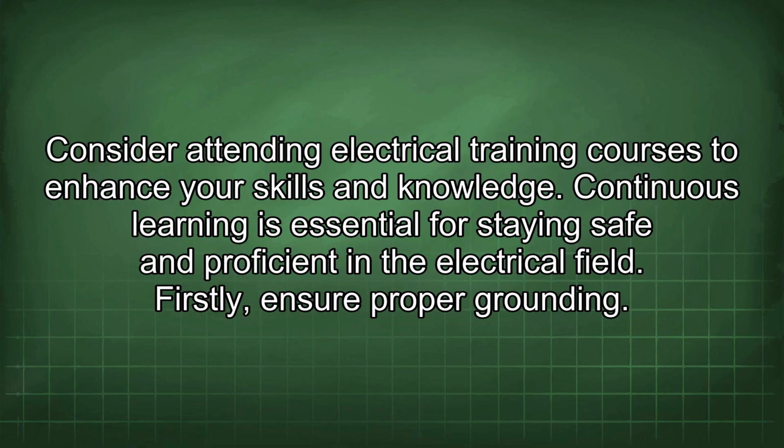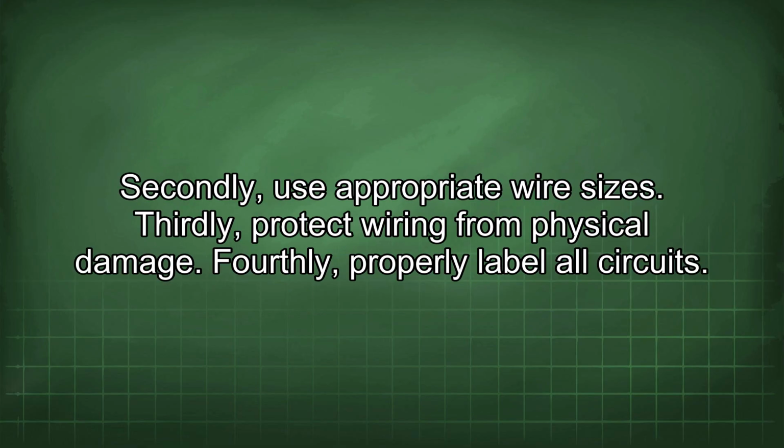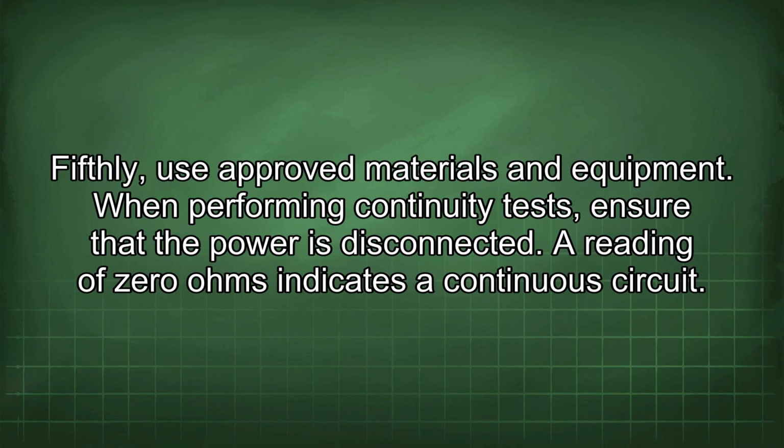Firstly, ensure proper grounding. Secondly, use appropriate wire sizes. Thirdly, protect wiring from physical damage. Fourthly, properly label all circuits. Fifthly, use approved materials and equipment.